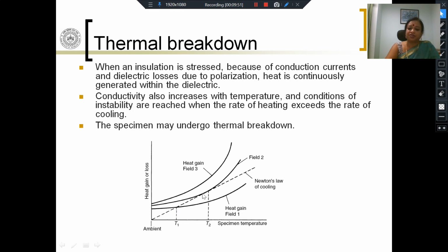So this is the characteristic of the material. Most of the time in power systems and power apparatus, whenever an insulating material fails, when you go and see what has happened, most of the time it has failed thermally because of overheating, and we have to make sure that thermal breakdowns can be controlled.